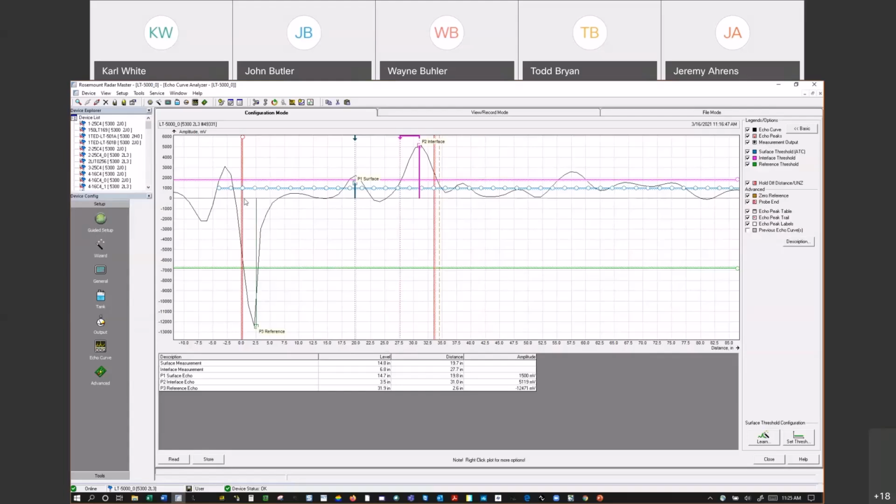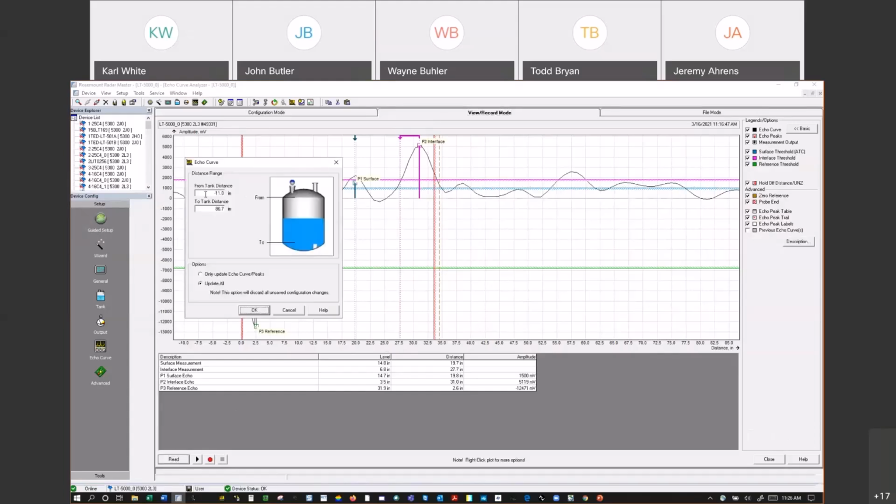Okay. So normally this would be the default, would be like -11 inches. This kind of shows us our spring pin connection. This is our reference pulse where that microwave travels onto the probe. There are times we'll ask you to read back maybe 60 inches. And you can do that by going to view and just doing read, we'll update this.